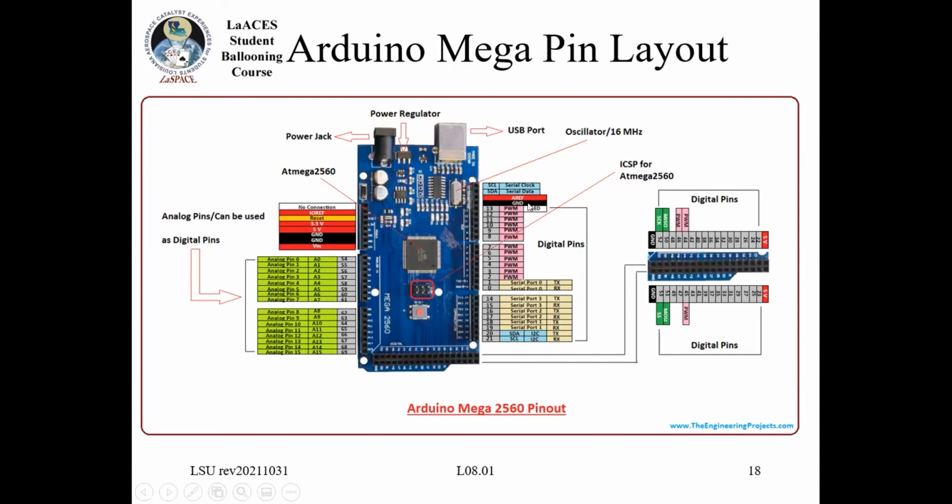If I want to use something more specific, like pulse width modulation or some of the serial protocols, I need to use these specific pins. But you can see here that they basically all have this gray pin number, including the ones on the bottom. And the gray here is indicating just a general purpose digital pin, i.e. I can flip each one of those pins on and off.